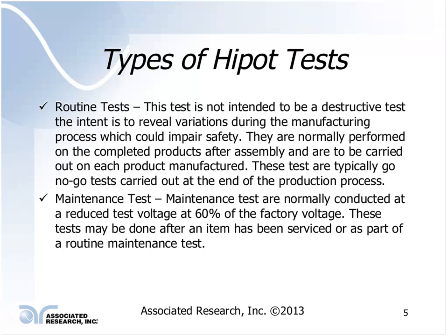One of the big things I think people fail to realize is many of the maintenance tests are done at a reduced voltage. A common test might be done at 60% of what the factory test voltage is.